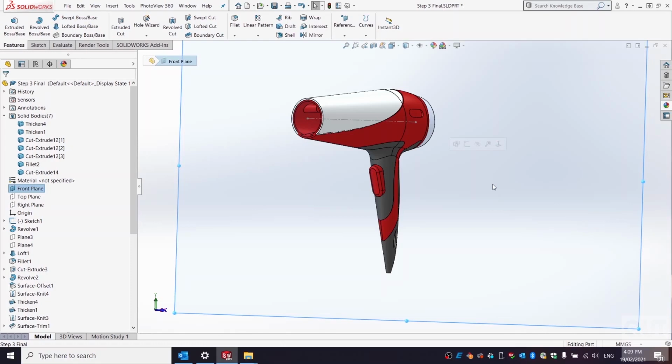And the reason for that is that these components can share the same geometry very easily. Then you can split them off into separate parts, put them into an assembly, then manipulate them independently and put independent features on them while they're a separate part.